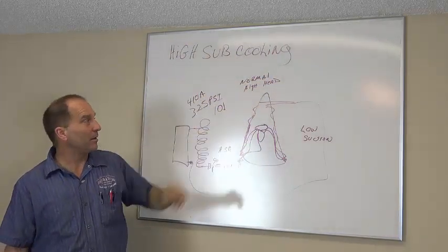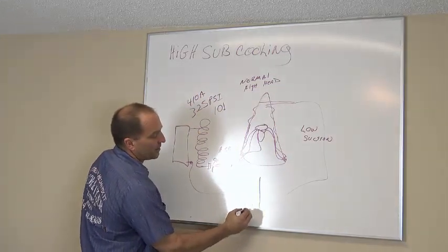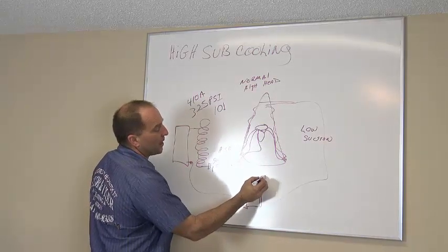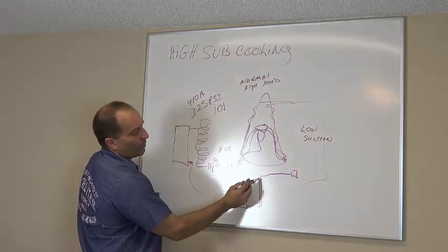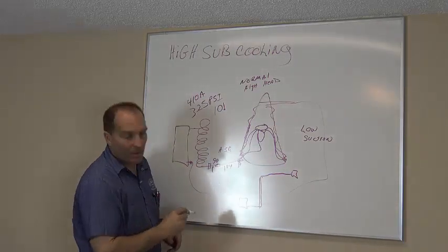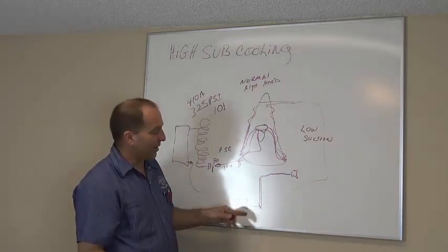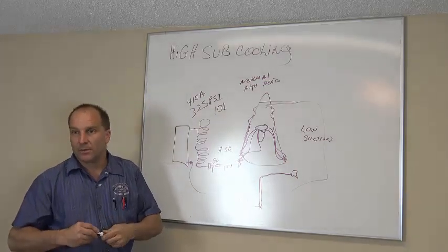And from here, so here's your wall, and your condenser sits out here, and your copper line runs through your wall, up, and then hits your top plate, and then runs over to your evaporator coil over here. Well, right here is where they kinked it. How are you going to tell from outside that you've got a kink at your top plate up there that was put in 8 years ago?